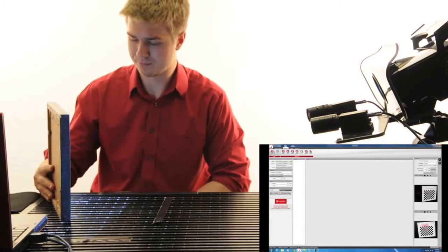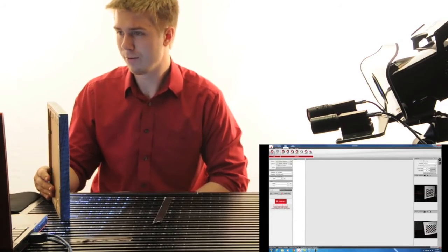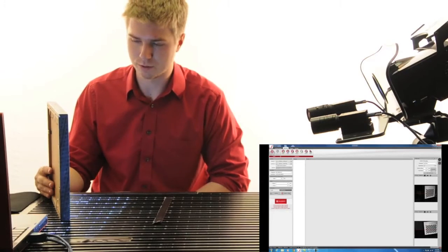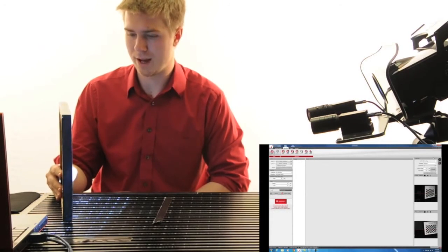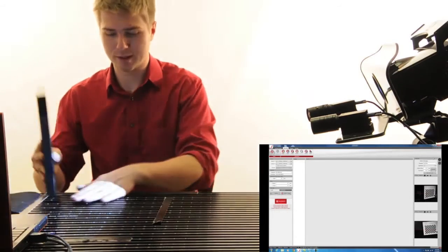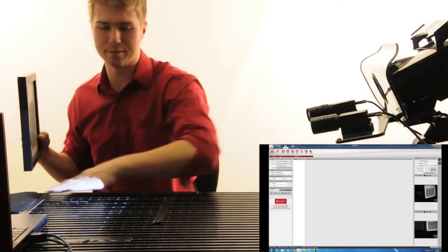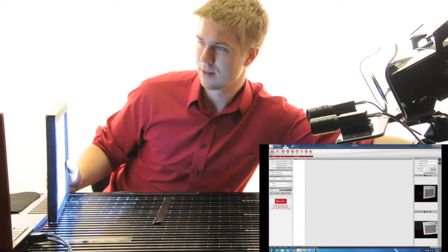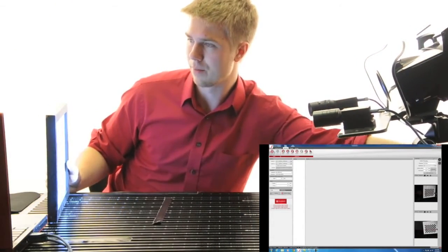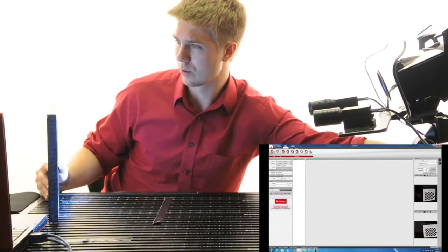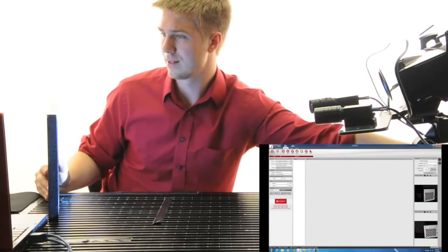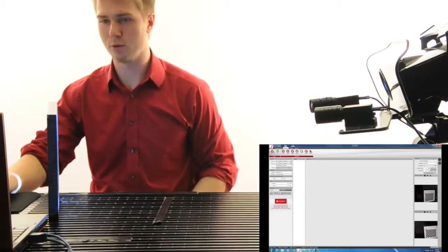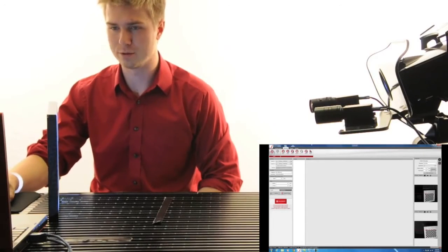So to fill in this area, what we want to do is, first we're going to want to take as many images as we can throughout this bottom section. So what I mean by that is we're going to tilt our camera up to where we're just capturing data in the bottommost portion of both views.